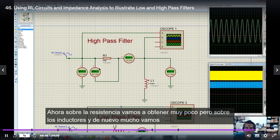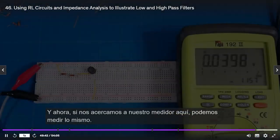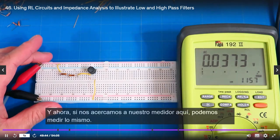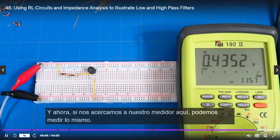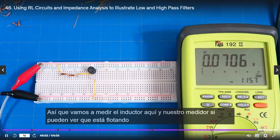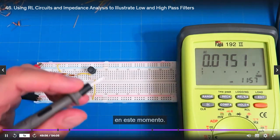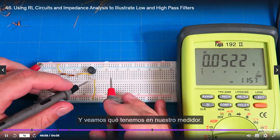Now over the resistor, we're going to get very little, but over the inductor, we're going to get a lot. We're going to get the majority of it, right? And so now if we go over to our meter here, we can measure that same thing. But again, our meter's bandwidth may be far, far exceeded by this point. So we're going to measure over the inductor here. And our meter, if you can see it, is just kind of floating around right now. And let's see what we get on our meter.